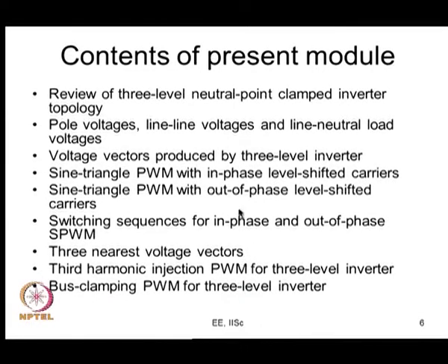And it is not just the sine triangle PWM; the 3 phase sinusoids you can compare with 2 level shifted in phase carriers. Then instead of a sine wave you can also add common mode. For example, you can add third harmonic to the sine, and have those 3 phase modulating waveforms with common mode added compared against these level shifted carriers. And instead of third harmonic injection, you can also go for bus clamping PWM, which we did in the context of 2 level inverter. Now we can do it in the context of 3 level inverter.